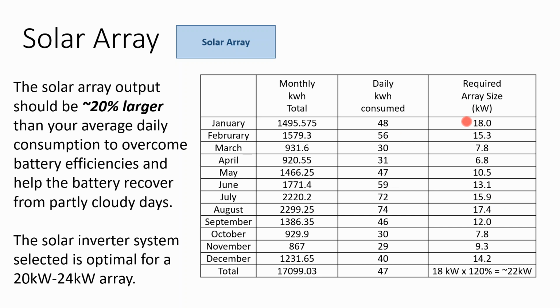And now that's just at the end of the month, your battery remains fully charged. But what we have to remember is that this is a day-to-day process because your weather cycles are a daily variance. You could go 5 or 6 days of overcast weather. So it's not just trying to settle up at the end of the month because I can't store a month's worth of electricity.